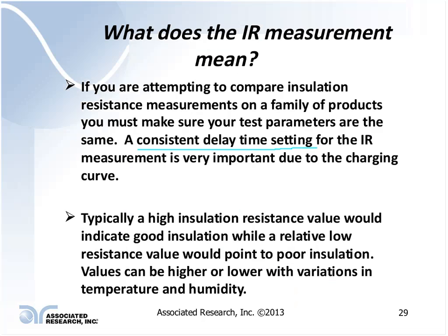Many insulation resistance testers have different capacity power sources. They have current limiting resistors that can vary how much charging current is available to charge up the capacitance of the product, which affects this delay time, which affects how fast the thing charges up.